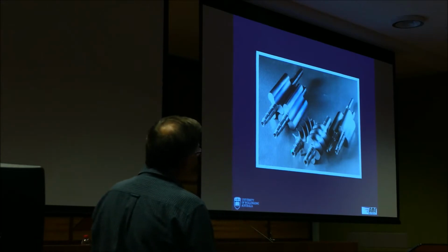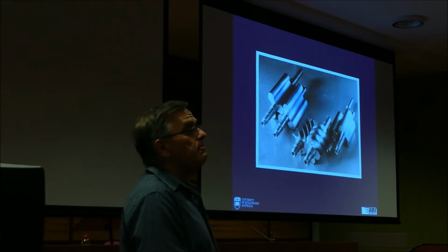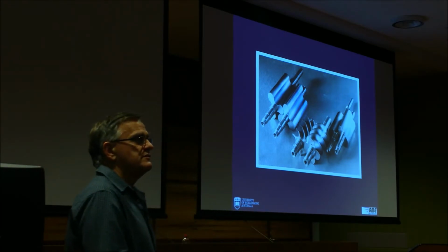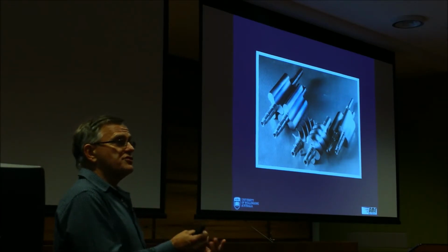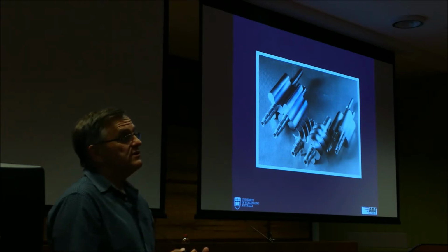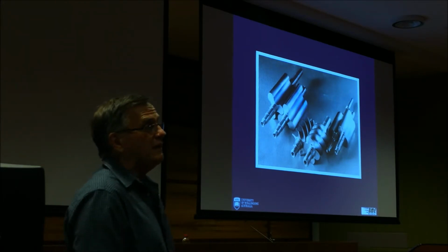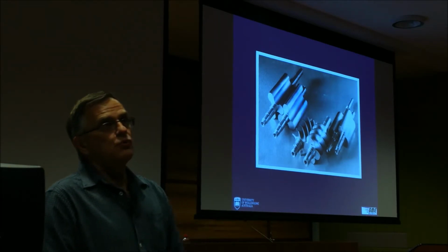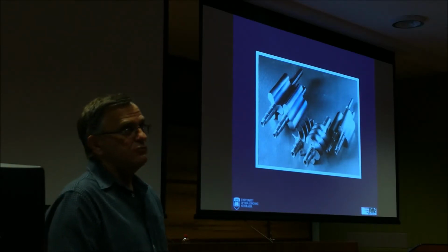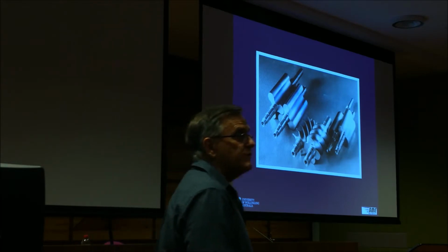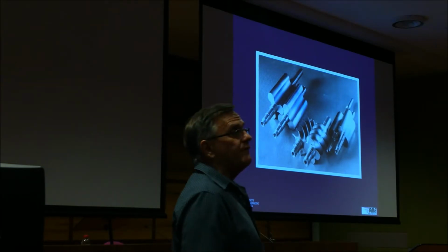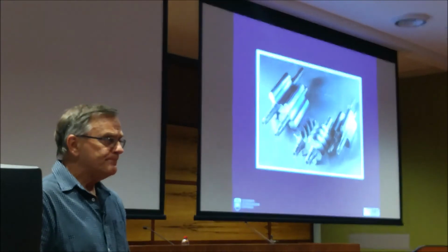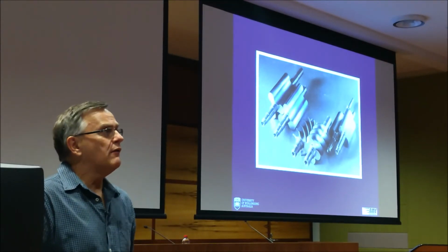Whereas in a compressor, let's say a rotary screw compressor, it will capture that air, compress it through the screw, and then discharge it. If you know anything about the compression cycle, that generates a lot of heat. So you get a lot of hot air coming out of these things. And when that air cools, you'll also get moisture being discharged. You'll reach your dew point. So with compressors, for pneumatic conveyance particularly, you generally need dryers to dry the air. Otherwise you'll get water running through your air lines.